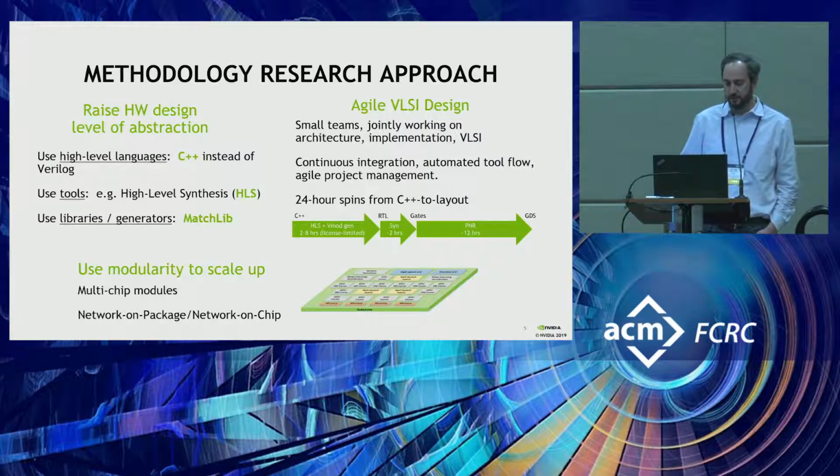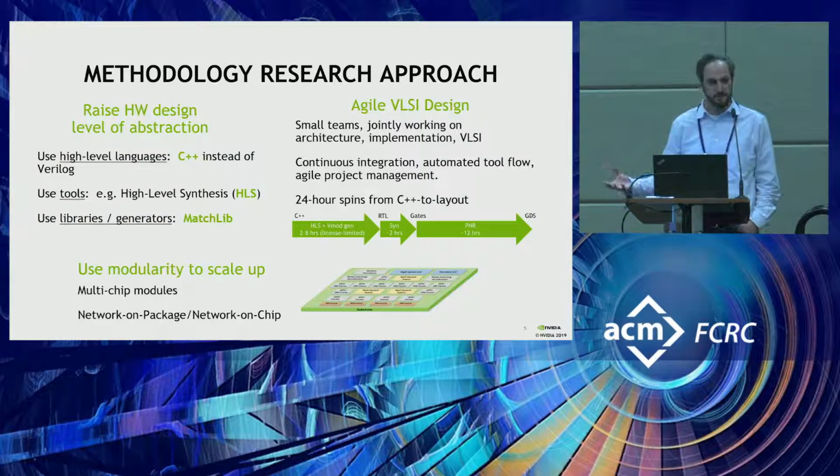I'm going to talk about 3 things. The first is trying to raise the level of abstraction that we're using for our hardware design. So instead of using manual RTL, let's use high-level languages. We've been using C++. Use tools, so we've been using high-level synthesis, although in a different way than the way Jason just described. And then the other key piece, which is sort of the part that we've been most actively working on as opposed to using third-party tools, is developing libraries and generators to promote reuse in the design flow.